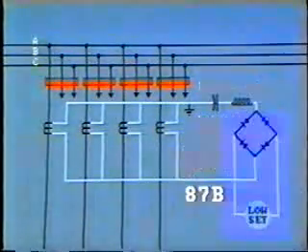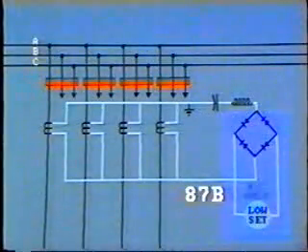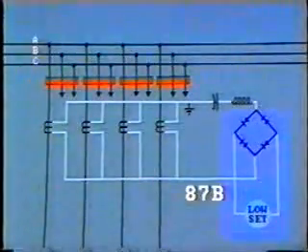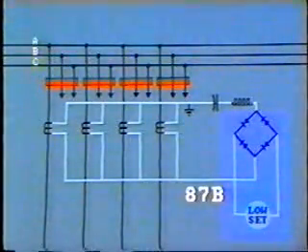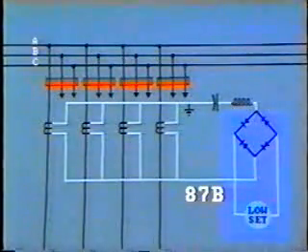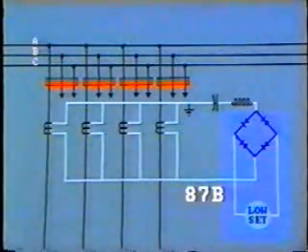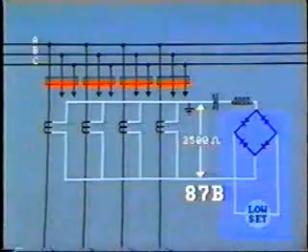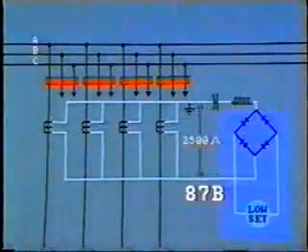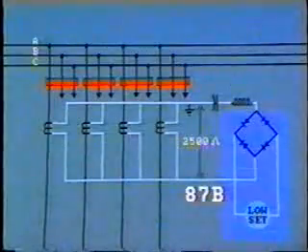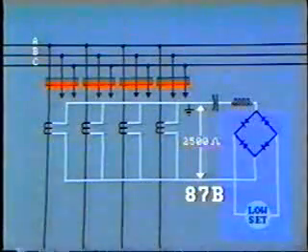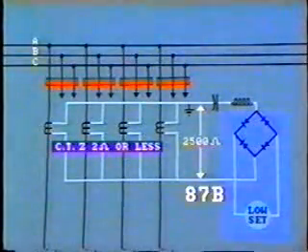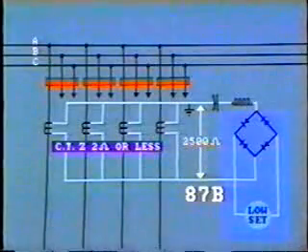In order to avoid this, a rectifier is placed in the circuit so that only DC current is fed to the relay operating coil. Now, adjustment of the coil will in no way affect the inductance of the tuned circuit. The effect of the rectifier and the resonant circuit raises the total impedance across the relay at this point to quite a high value, usually around 2,500 ohms. This has another advantage. Note that this impedance is far, far greater than the impedance of the CTs, which is probably about 2 ohms or less.